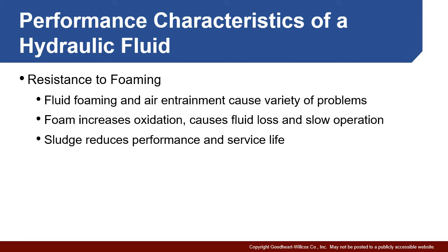Keep in mind foam. Again, you're exposing the oil to all that air and oxygen in the foam. If this is drawn in, that potentially is going to affect your operation. You're going to have air in the lines, which is problematic. So that's a concern. And keep in mind, as that oxidation occurs, you will eventually get a sludgy material that is very problematic.